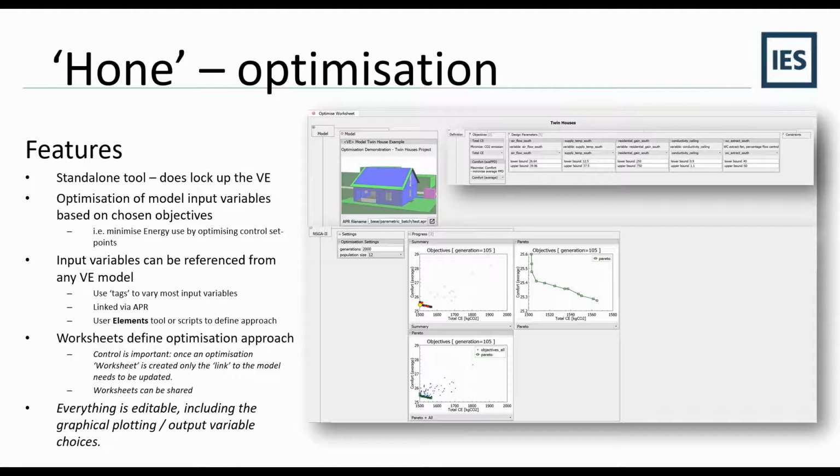For example, instead of setting up a single simulation to run where everything is fixed values, instead of putting in a fixed value, think about an HVAC set point and what minimum and maximum values you could get away with within that particular design. You could then put that in and put in intervals for studies within that. Think about orientation, for example, being able to orientate from 0 to 360 degrees as minimum and maximum, and then do simulations at every degree step. So you would do 360 simulations in that stage.